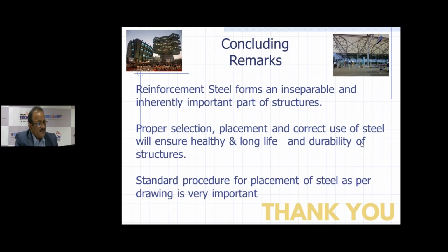So the significance is that before the steel bars are used at the site, they are tested for this bending, and it should not crack during the bending, and it should not fail in a brittle manner. So that is why it is done.